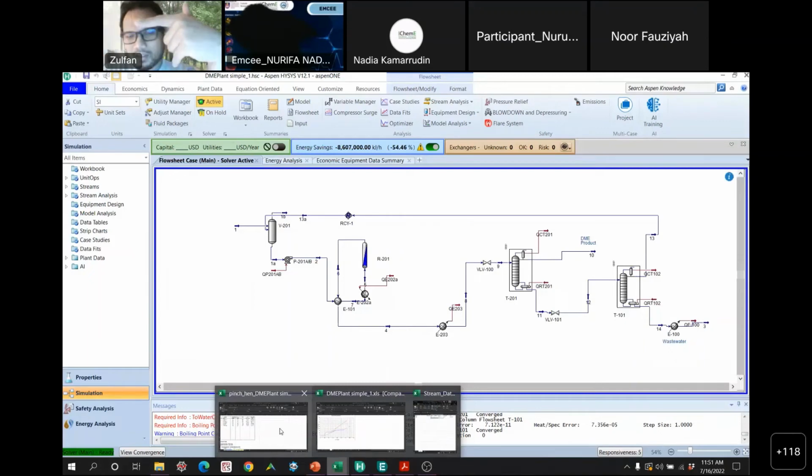In this case, it is 6 megawatts of total heating. You get the hot streams and cold streams into one of these Excels, so you get to know the targeting of the minimum hot utility or minimum cold utility that you can achieve theoretically. So in this case, it's about 1 megawatt. Yeah, so that's why we know the 5 megawatts potential to be reduced.